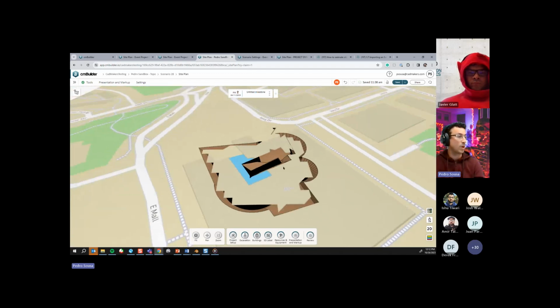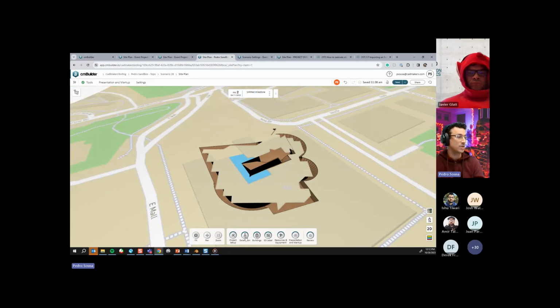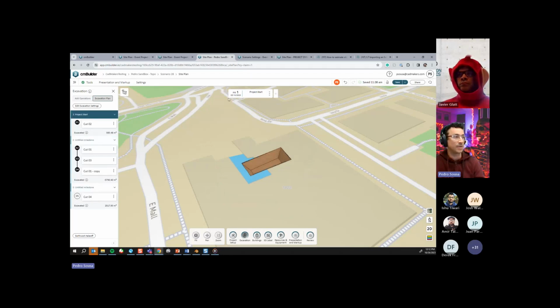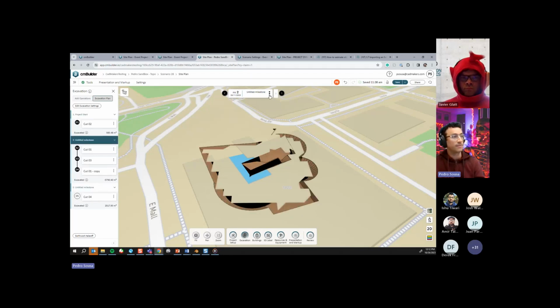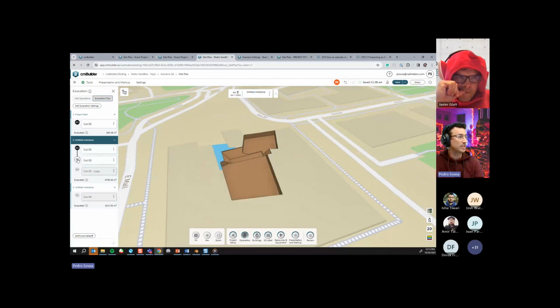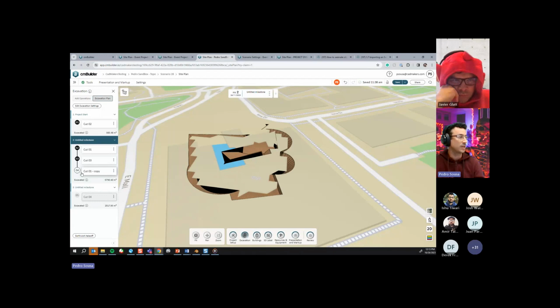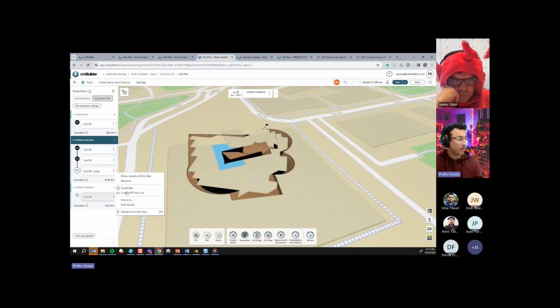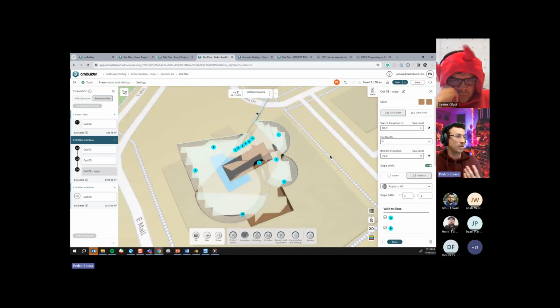And then if I wanted to debug this, I would go into my excavation, go into excavation plan, and I can see over here my steps, but I know that the problem is happening on my milestone number 2. So when I flip to milestone number 2, I'm going to see that broken geometry. I can click on these buttons over here to see what shape is creating that problem. So if I click on cut 1, I notice that the shape creating the problem is this one. So then I'm going to go inside and debug what's going on over here.